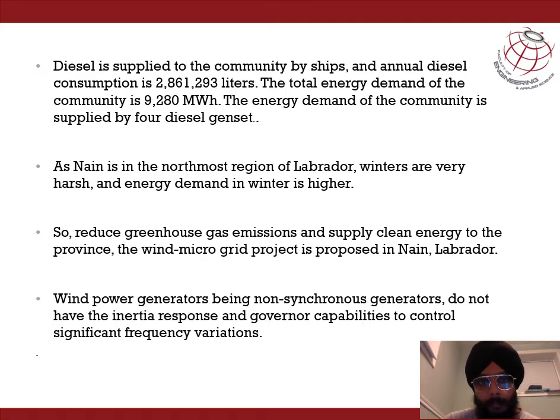So diesel is brought directly to this community by ships, and the energy demand of the community is supplied by three generator gensets. Wind power generators, being non-synchronous generators, do not have inertia response and governor capabilities to control significant frequency variations.